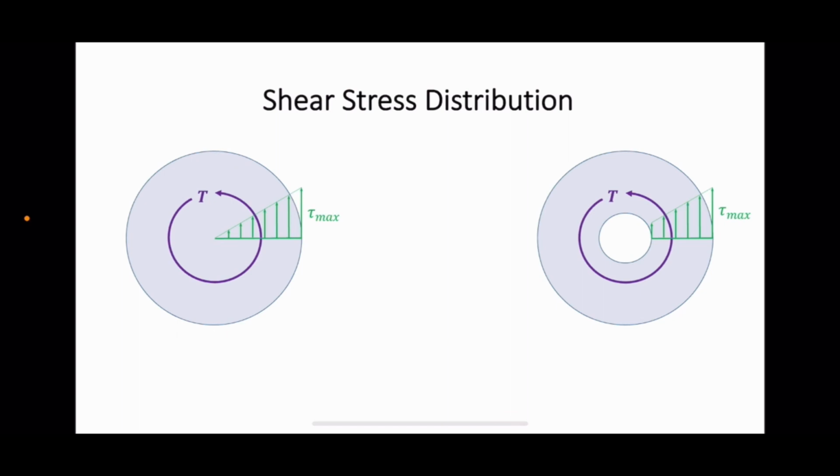While this gives us an impression that the shaft tends to fail at the cross-section because of shear failure, that is not the case for a shaft made of wood, which tends to split along the axial plane. This mode of failure can be explained easily if you recall a very important property of shear stress that we learned before, the so-called complementary property of shear.